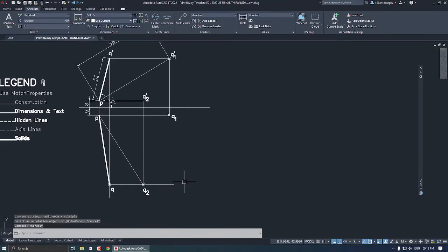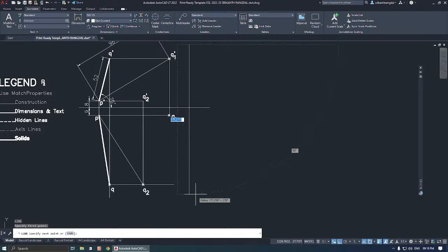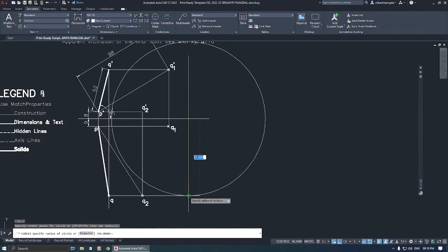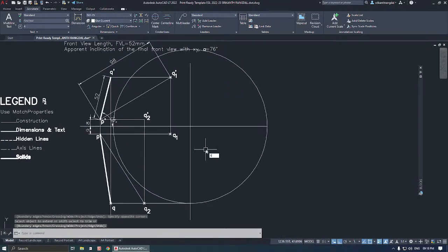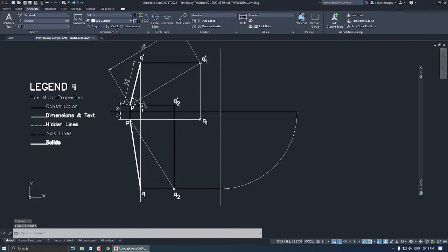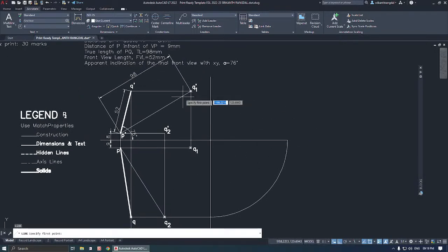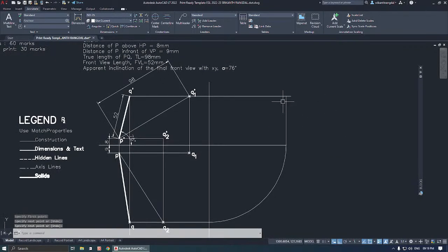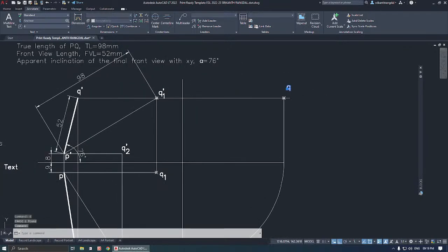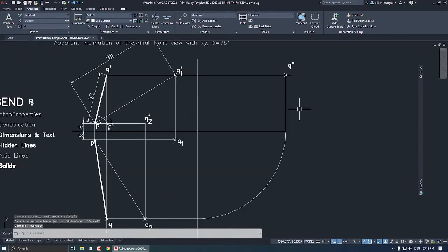Okay. If you want to continue and go ahead with the side view, you have to draw the x1 y1 line. You have to extend this up to here. You have to take an arc here. Okay. Extend it. Okay, then trim it. Fine. Now the Q point is coming over here, and the Q point is also coming from here. These two should intersect. So where do they intersect? What is this point? This point is Q double dash.